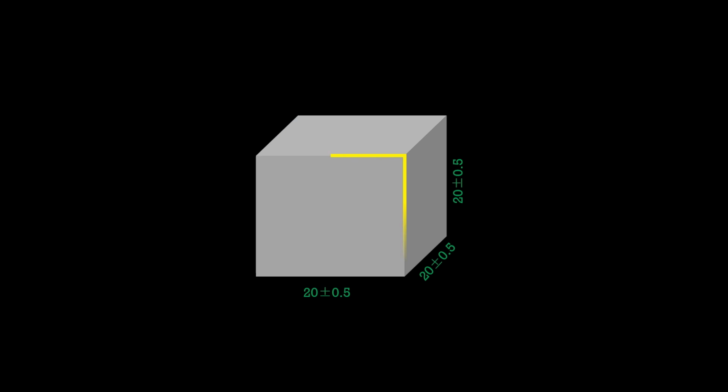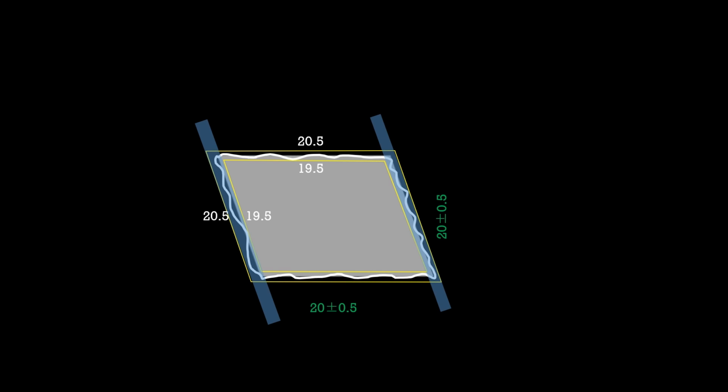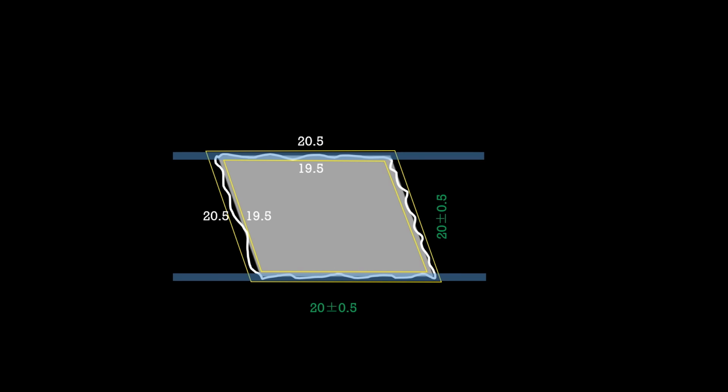As we have seen in the cubic block example, the square profile is an irregular feature of size because it has an actual mating envelope, but GD&T Rule 1 only applies to the width and the height as a regular feature of size because they are sets of two parallel and opposed surfaces. But other feature of size benefits are also given to irregular features of size.